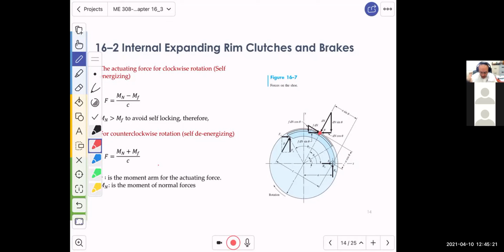We're taking one single element. There will be a normal force. The normal force has to be perpendicular to the tangent, and there is a friction force which is acting along the tangent. Now what are we going to do? We will resolve the normal force into two components, and we will resolve the frictional force into two components, sine and cosine, sine and cosine.